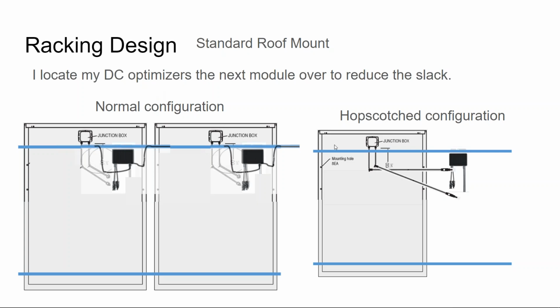Then my module clips come in, and there's a clip that goes between each module along the rail to secure the module into the rail. Because I already have my cable inside that rail, the module clip secures the cable into the rail, so there's no way that the cable can come out. Rather than using a tie wrap or a cable clip, I've physically secured all but the very last little whip into the rail, and my cable is hidden inside the rail all the way across.